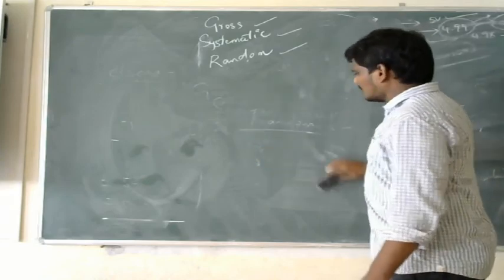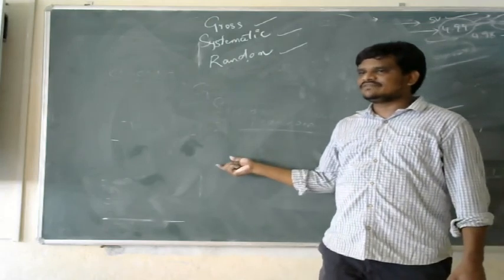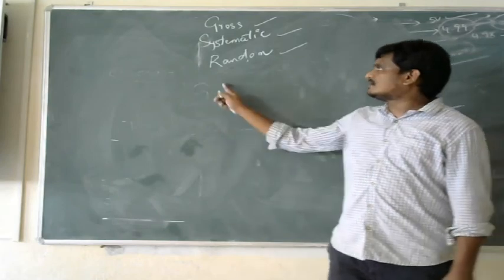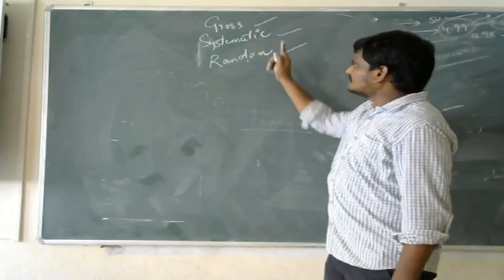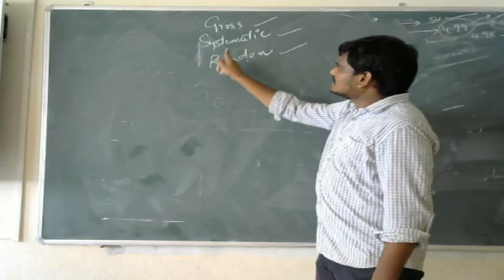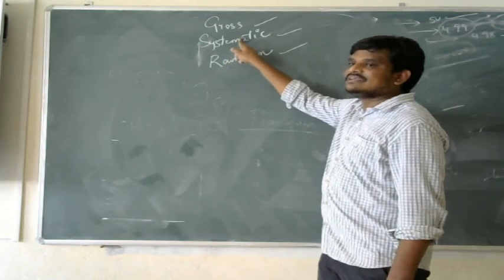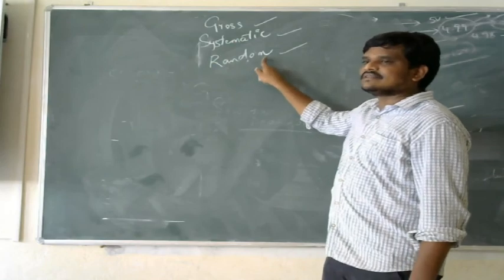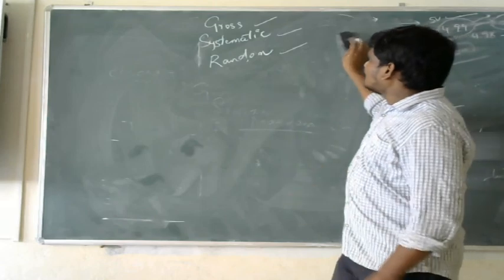Before concluding the topic, I am going to define error again. It is given as the difference or deviation between the true value and the measured value of a particular instrument. Errors have been classified into 3 types: gross errors, systematic errors and random errors. Gross errors are mainly due to human mistakes. Systematic errors are mainly due to manufacturing errors or the design of an equipment, and random errors are mainly due to noise and other sound effects created in the surroundings. These are the major types of